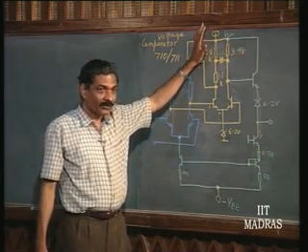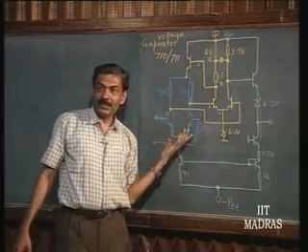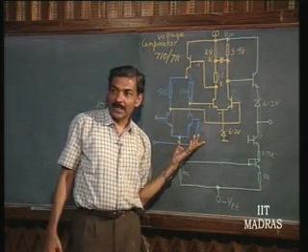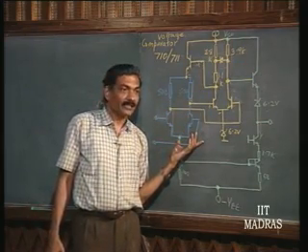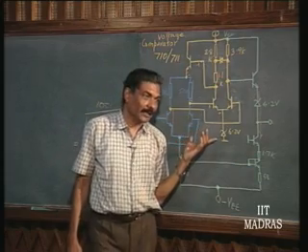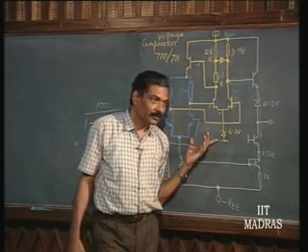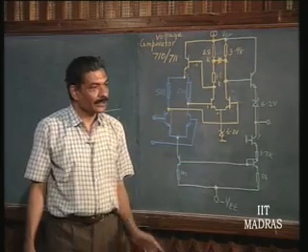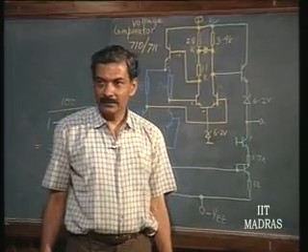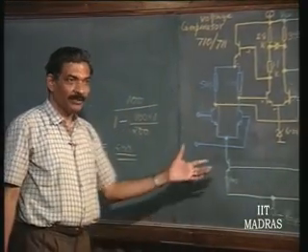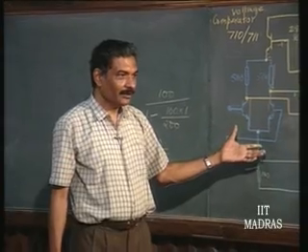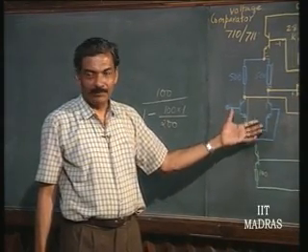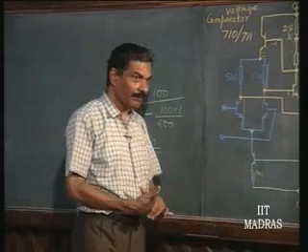Okay. Therefore, whenever you use comparators in a practical circuit and also in open loop, you have to be extremely careful about power supply lines also. Okay. So, this cannot be used in negative feedback. This can be used in positive feedback mode without any problem, but not in negative feedback. No, none of the comparators.